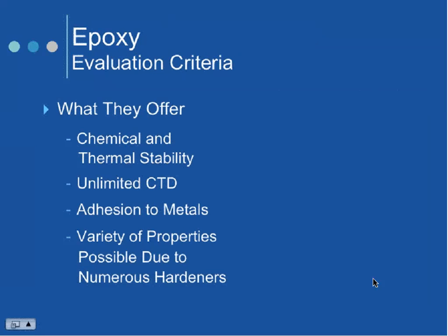So we always like to look at the evaluation criteria, what they offer versus other chemistries. Again, most customers pick epoxies because of their chemical and thermal capabilities. They need to go there because they have a higher temperature that they need to achieve, or sometimes it's the gaps, the cure-through depth. You could fill this whole room with epoxy. It might be on fire because of the exothermic reaction, but they will fill very large gaps.